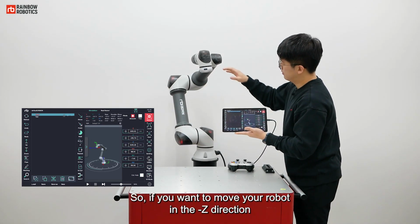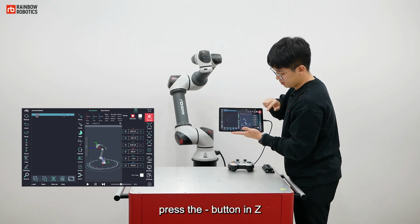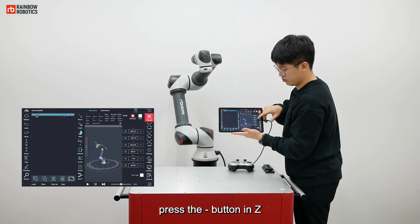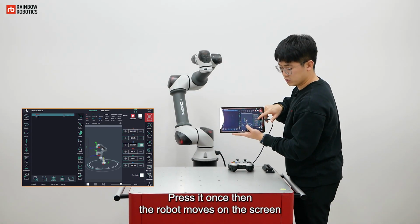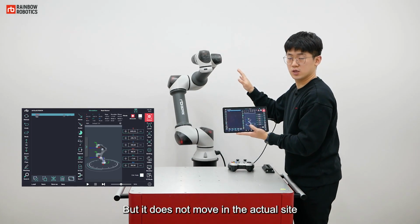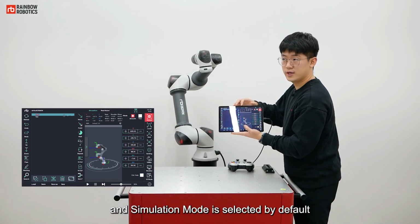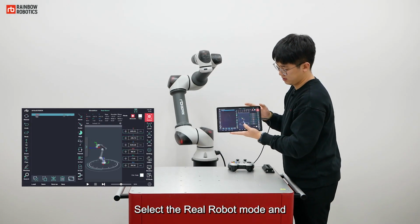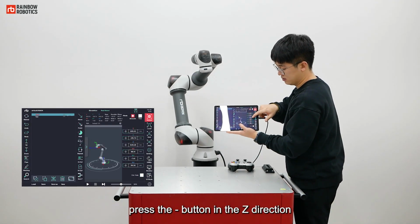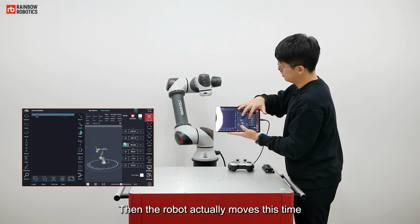So, if you want to move your robot in the Z direction, press the button in Z. Press it once, then the robot moves on the screen. But it does not move in the actual site. Why? Because at the top of the screen, the simulation and real robot modes exist, and simulation mode is selected by default. Select the real robot mode and press the button in the Z direction. Then the robot actually moves this time.